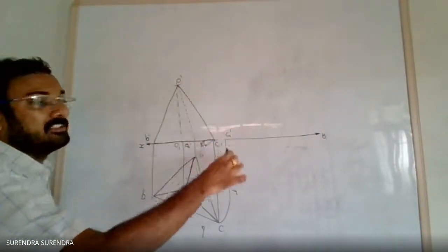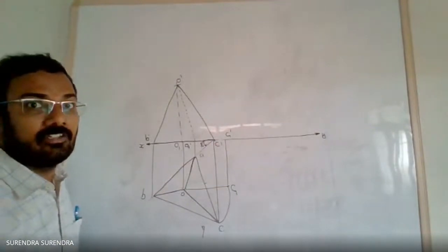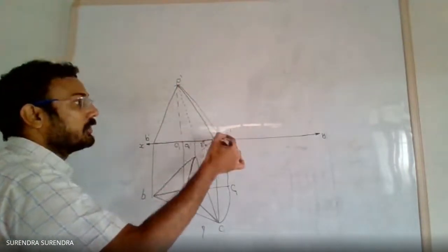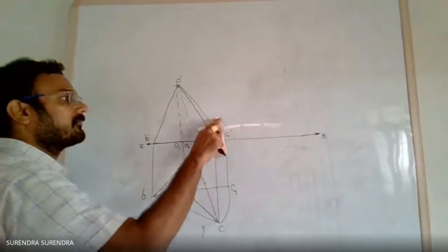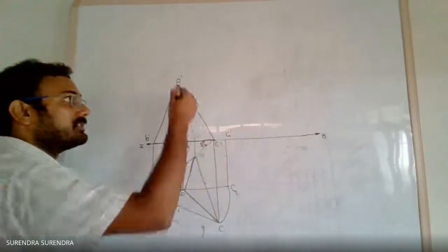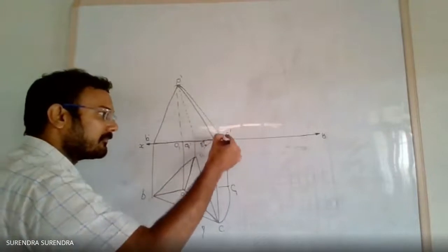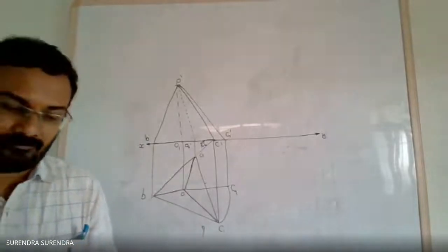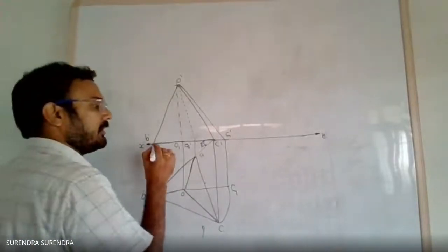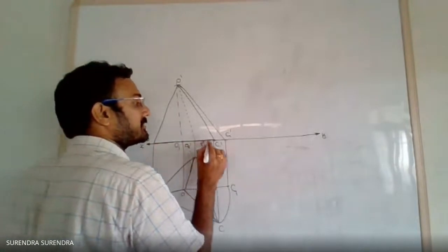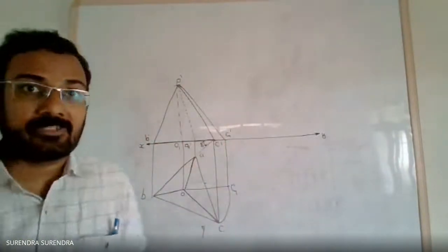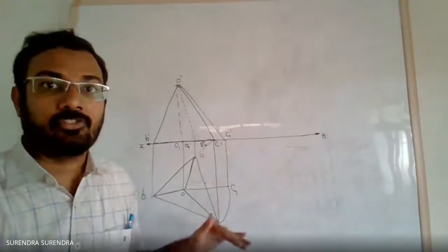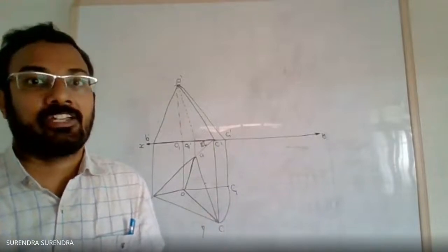No need to draw the line C1 dash O dash, just show it or draw it with a 2H pencil. Draw all these lines with HB. Only the C1 dash O dash line is drawn with a 2H pencil, as it is only the construction line for calculating the axis height. So you should follow this process for a tetrahedron.